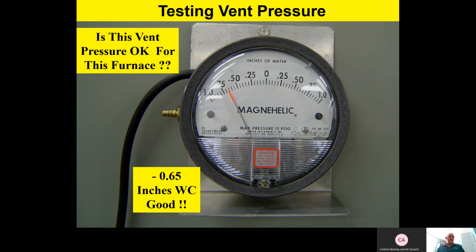Now, team, this is really, really important to remember. This is just a rule of thumb, and I don't like giving a lot of rules of thumb because it can vary so much, but as a general rule, if the vent pipe is the proper size and you haven't exceeded the length in the venting tables, typically our Champion furnaces will close that pressure switch with enough pressure to close the switch plus about 25 to 50%.